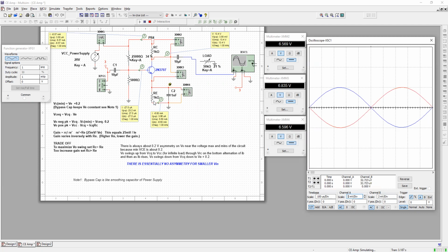So we have reduced our effective gain. We have removed some of the stability at the emitter resistor as far as the AC isolation. It's going to see some of that AC current. And it's not working as well as we would have liked. So let's go back to the larger capacitor.